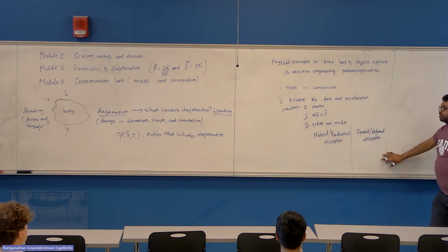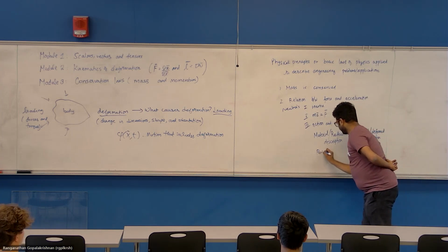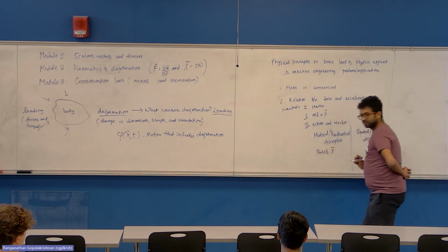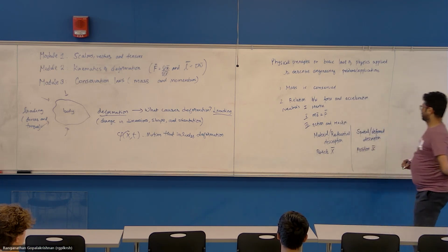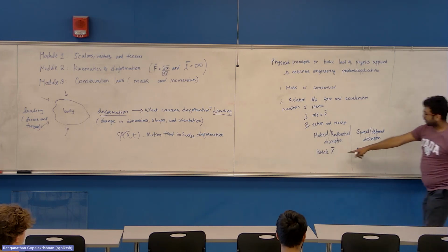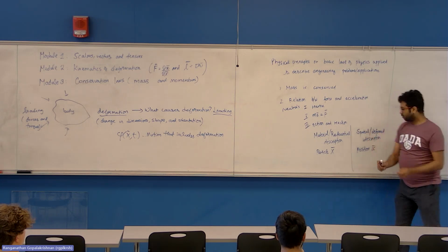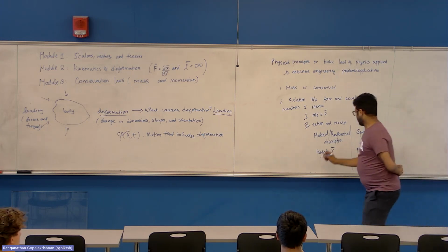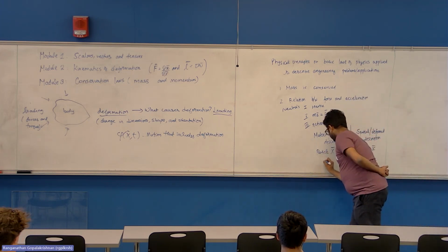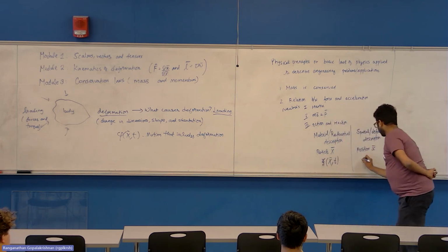I'm summarizing what you know already from module 2, where we talked about a particle denoted by uppercase X, a position denoted by lowercase x. What is uppercase X? It is the union of all the positions occupied by the particle, whereas x is just a point in space. Okay. And then we also have a quantity g, which may be expressed in the material form g of X comma t, or in spatial form g of x comma t.